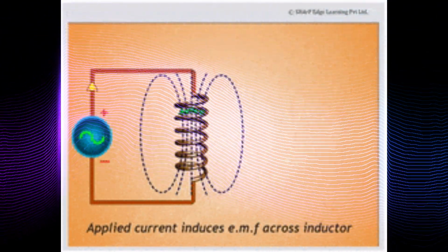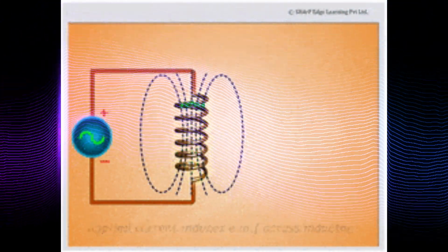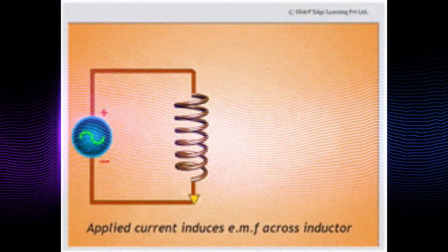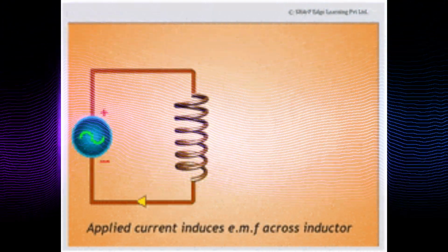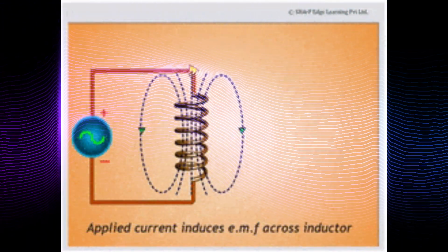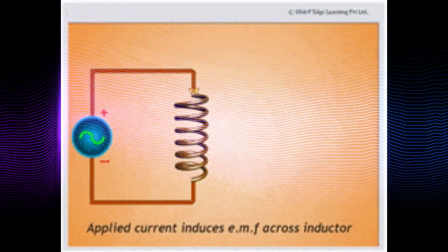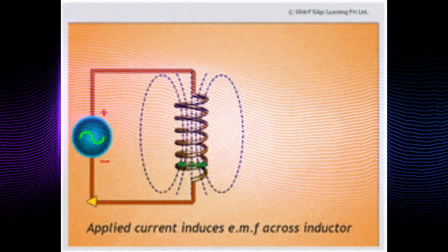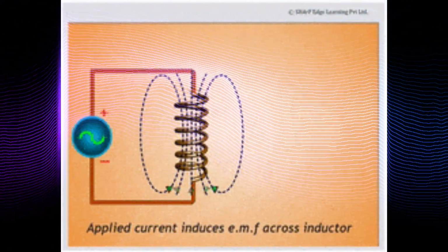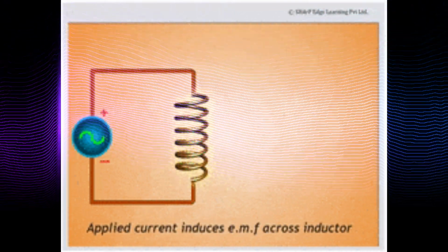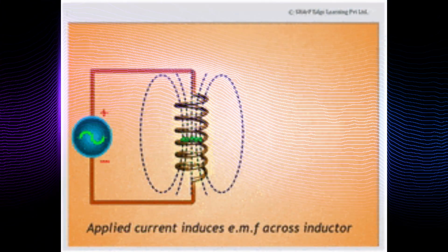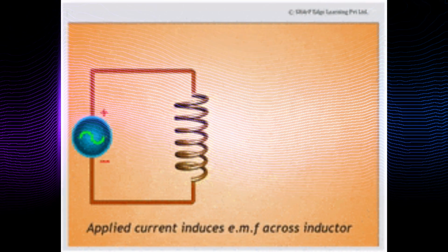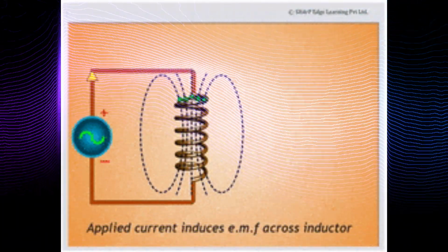Now, assume that the coil is connected to a 120 volts AC circuit, and an ammeter measures a current flow of 0.8 amps. Ohm's law can now be used to determine the amount of voltage necessary to push 0.8 amps of current through 6 ohms of resistance. E, which stands for voltage, equals I times R. I stands for amps and R for resistance.